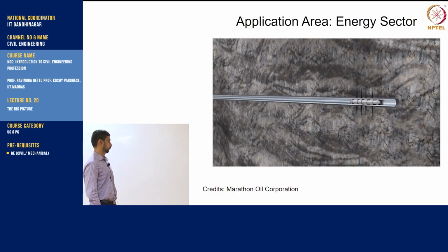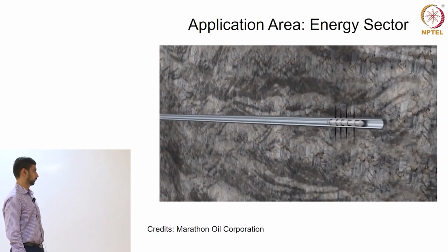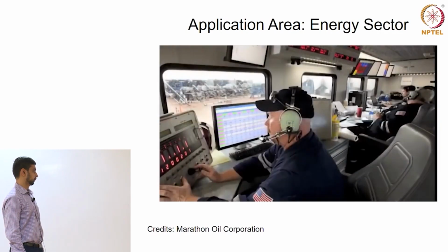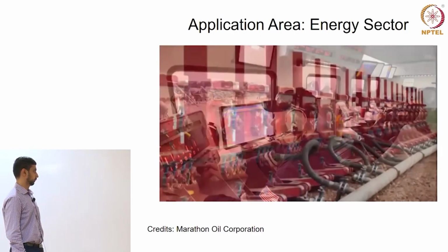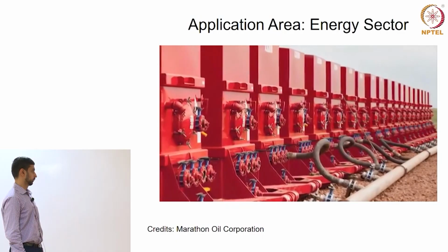Since these perforations are only a few inches long and are performed more than a mile underground, the entire process is imperceptible on the surface. The perforation gun is then removed in preparation for the next step, hydraulic fracturing. The process consists of pumping a mixture of mostly water and sand, plus a few chemicals, under controlled conditions into